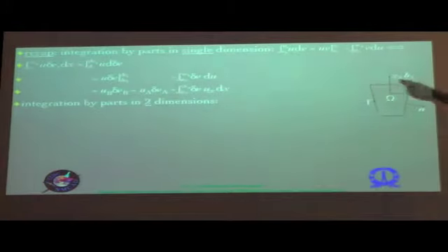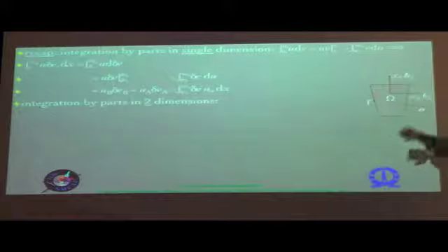So this is basically what we have, a domain omega, which is the cross sectional domain, it could be any shape. As of now, we are focusing on class R beams where there is no difference in order of magnitude in the two directions. That's basically taken into account. You would have a closed contour, which is the boundary of that particular cross section. Even when you had, for example, class T beams here, an I section, you would still have a single contour that you're basically going through.